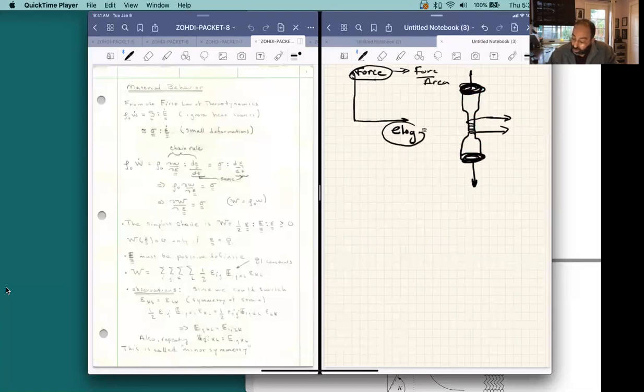And the elongation will also be some kind of percentage difference of the original length and the current length, normalized by the original length. So it's going to be some type of non-dimensional number. And those two things, stress, which is usually going to be newtons per meter squared, versus some type of dimensionless quantity, let's call it meters per meter just to give it some units, but of course it's dimensionless, we'll see some kind of readout that usually looks like this.